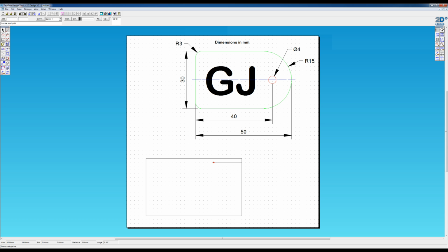15. And then from that point, we're just going to go straight down. Next job is to click on this bottom horizontal line and come up 15 again. And then clicking across. And where these two lines intersect is where the center of this radius is going to be. So before we draw anything else, we'll just keep the drawing tidy and get rid of these two lines.